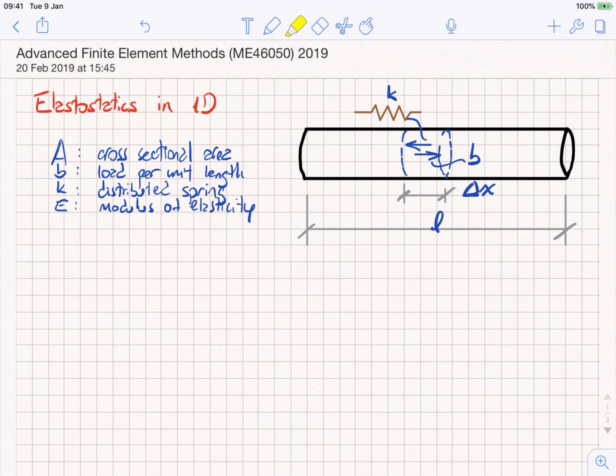So in a way, if you have a positive displacement of the bar, that force is going to be contrary to the movement, so it's going to have a negative direction, right? And then we're going to assume that the bar behaves linearly. We assume that it's therefore Hooke's law, and that therefore strains are related to stresses linearly as well.